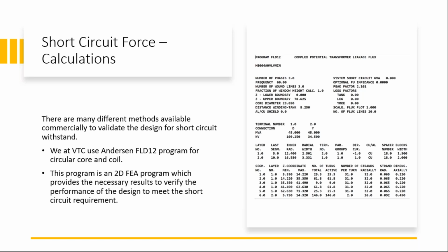And again, the calculations will be different for different types of transformer. For example, if a transformer is a delta-Y transformer, DYN1 or DYN11, the three-phase short circuit is most severe, so the three-phase short circuit will be carried out. But whenever we have YY delta transformers, single line to ground fault is most severe.